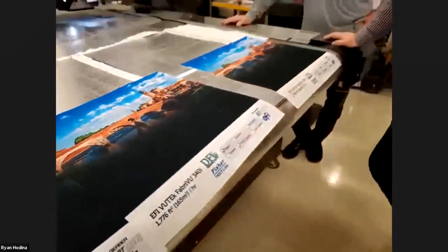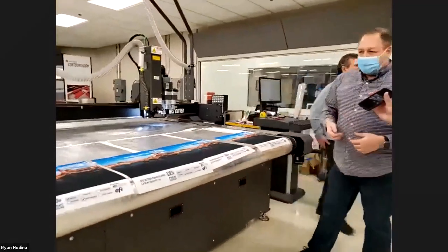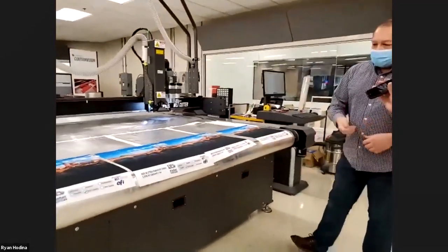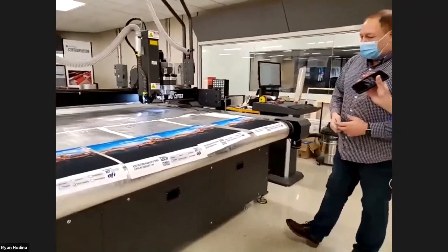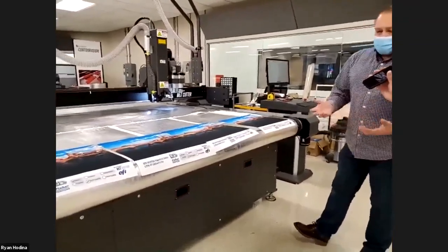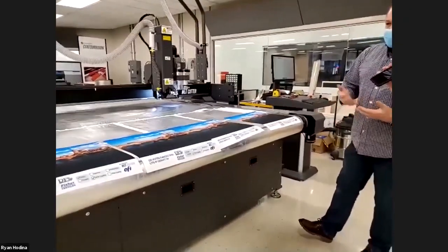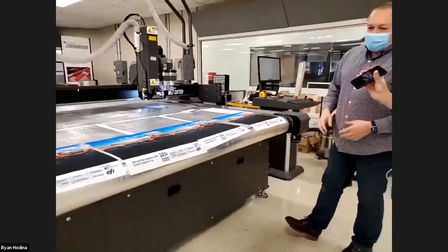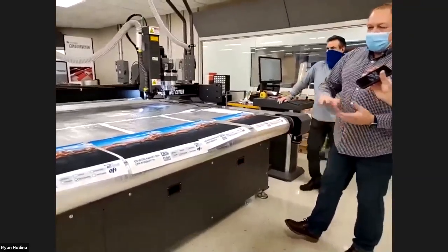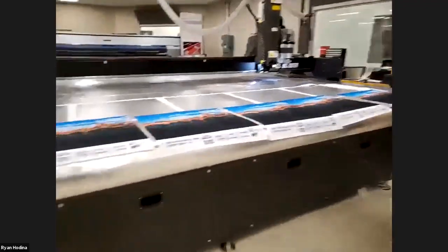So yeah, so as Mark said, of course, some materials you absolutely need to have a sealed edge. So if you're doing hand cutting, you'd be using some kind of a hot knife. But for automated cutting, the primary tool is to use a laser. Beautiful thing with the laser is there's no mechanical blade or tool in contact with the material. So there's no chance of you pushing the material or miscutting a thread or a fiber or anything like that. It's going to almost always give you a very, very good quality cut.